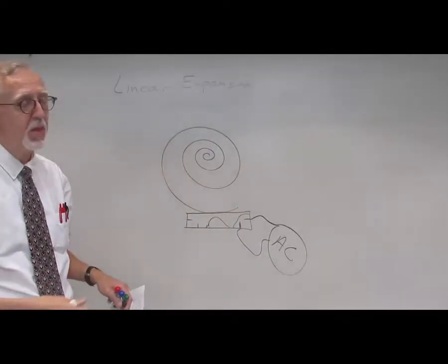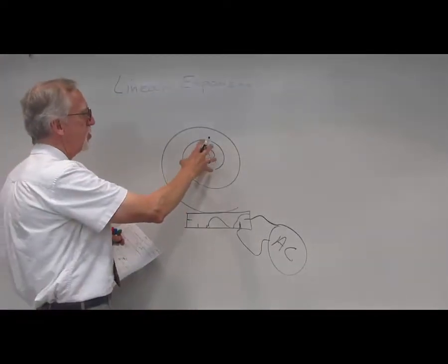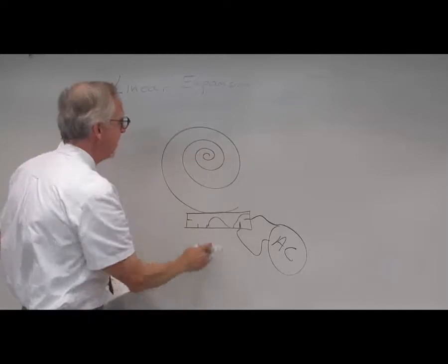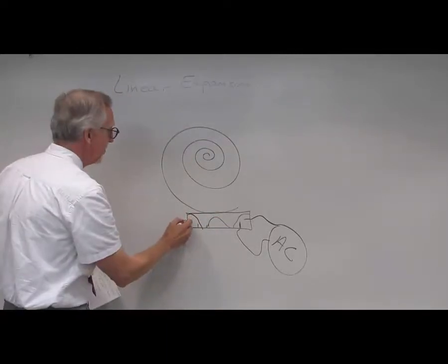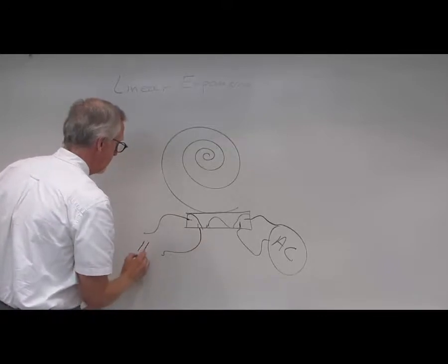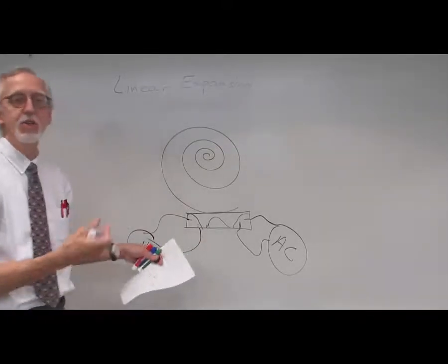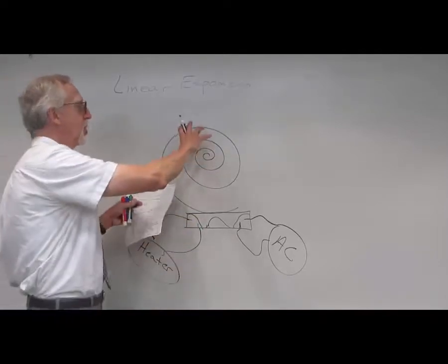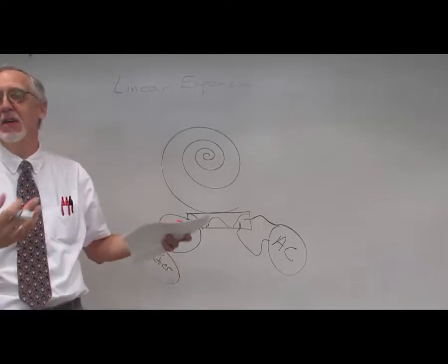would go off. And then in the winter time, if this coil got too cold and contracted, the mercury would flow down to this end, would connect these 2. These were then connected to a heater. Your heater would turn on, warm up the house, the coil would rotate back, the mercury would flow off the terminals, and the heater would turn off.